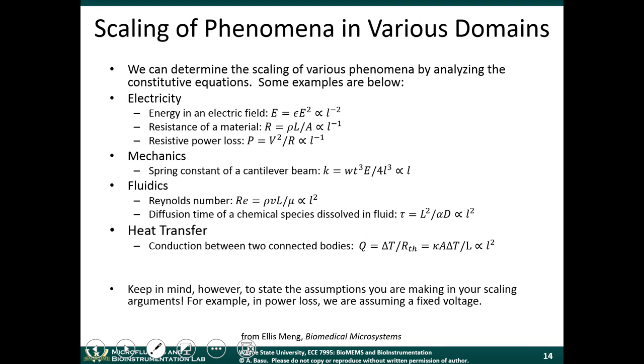Okay, so going into some standard things in fluidics and heat transfer. Reynolds number. The Reynolds number is the ratio of inertial forces divided by viscous forces on a packet of fluid. What happens if you have a lot of viscous force and no inertial force? Then the flow is laminar. Predictable flow patterns, no turbulence. Turbulence is where you have unsteady flow patterns, things that change with time. Turbulence in a plane, you've experienced. Right?